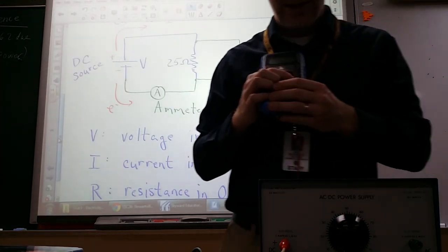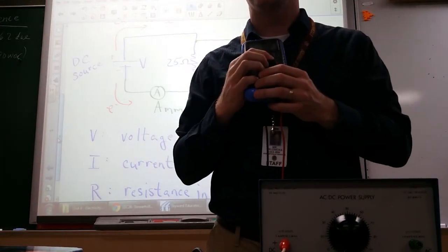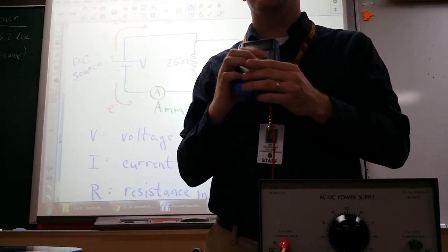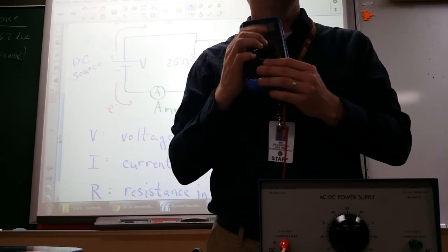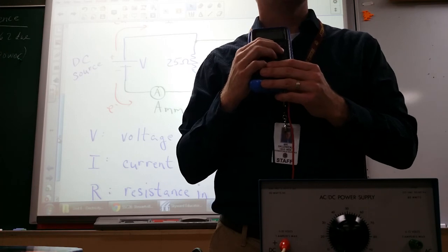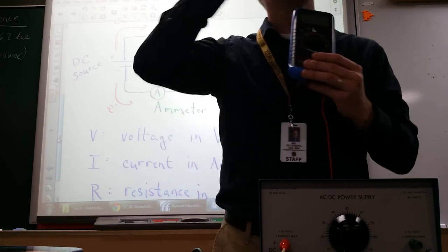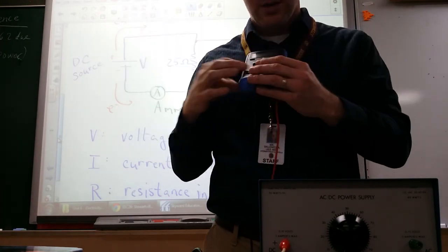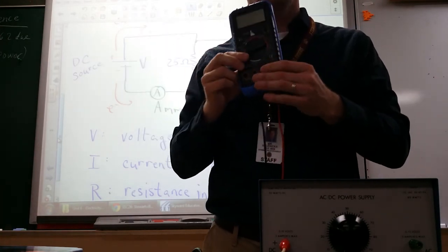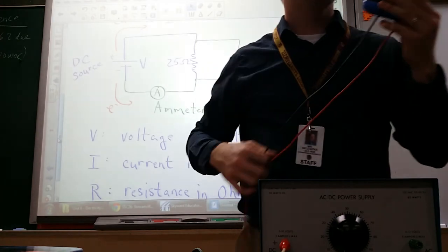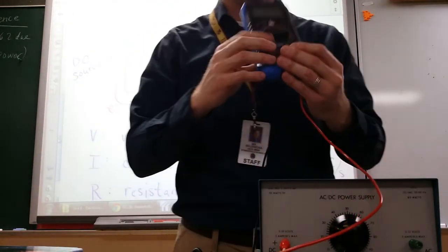The dial gets set based on what measurement you're making too. And you'll notice that we have two V's over on the right. One with a pair of straight lines and one with a squiggly line. The straight line means direct current. The squiggly line means alternating current, because if you looked at the voltage, it's actually a sine wave. So we're setting up into the direct current.